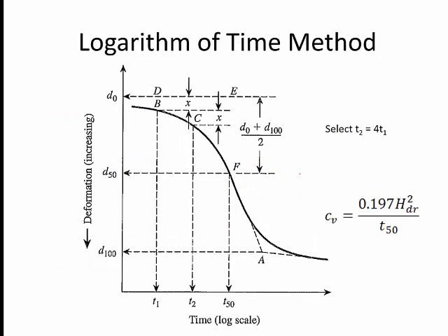So the log of time method is usually utilized in a clay type material where it takes a long time for consolidation to occur. And as you can see, the deformation increases downward over time in a log scale.